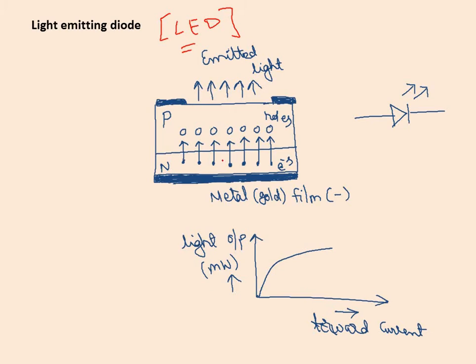As soon as the conduction band electrons from the N region cross the barrier and enter the P region, they recombine with the holes. Similarly, some holes from the P region may try to cross the junction, but a conduction band electron may fall into a hole before the hole crosses the junction because of the electric field which was developed there. In either case, a recombination of the electron and hole takes place.